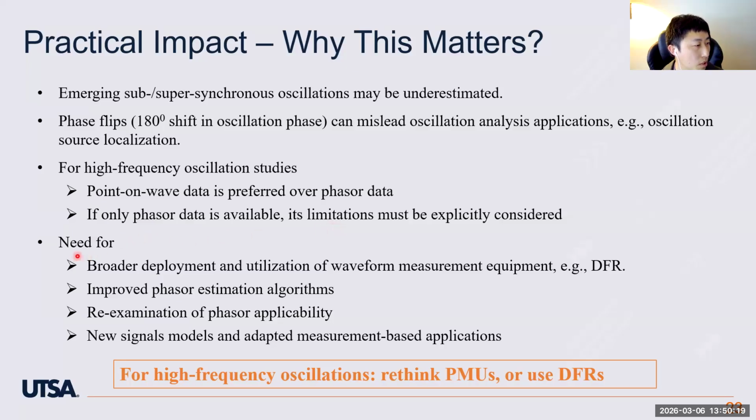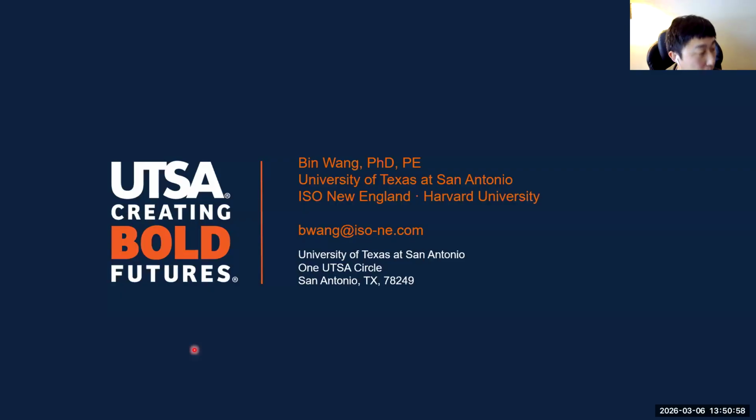In the future, we need more deployment and utilization of waveform measurement equipment like digital fault recorders. We need to improve our phasor estimation algorithms. We need to revisit the definition of the phasor concept and whether it still applies to power system high frequency oscillation signals. And maybe we also need to propose new signal models to better represent high frequency oscillations and adapt existing applications to those new models. With that, I conclude my talk and am ready for questions and discussions.